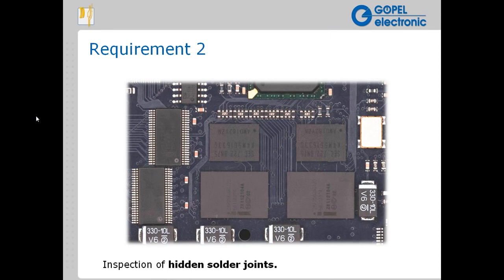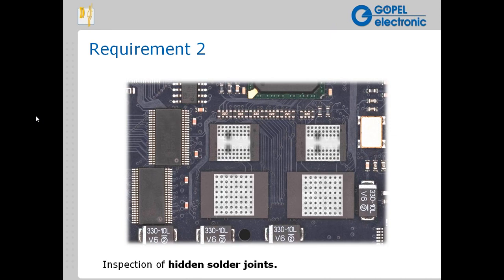Another requirement is top and bottom inspection, and looking at the same example here, you can see that we have actually transitioned through the layers of the X-ray image. Again, we're talking about 3D X-ray here, and with 3D X-ray we image the device from multiple different angles, and this gives us the ability to actually separate the Z-axis. So we can see separate components on the top, we can see separate components on the bottom, we can see the solder joints, etc. So we can actually do top and bottom inspection in one pass with X-ray.